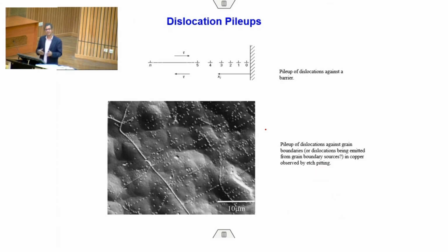So, because of these two aspects, one is that the grain boundary structure is different, and the other is that the grains are not oriented the same way, dislocations moving in one grain will not be able to directly move into the other grain. That means dislocations will find the grain boundary as an obstacle. You can also imagine a dislocation can jump over and reach the other grain.